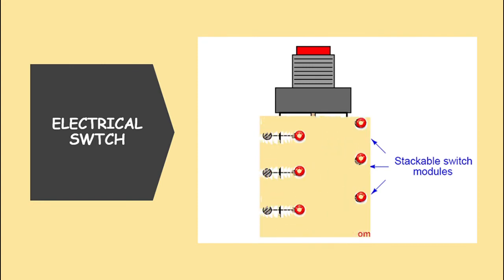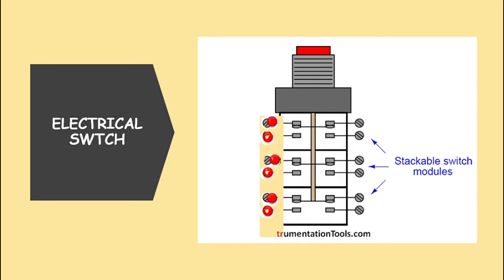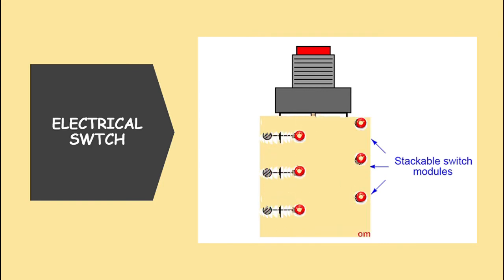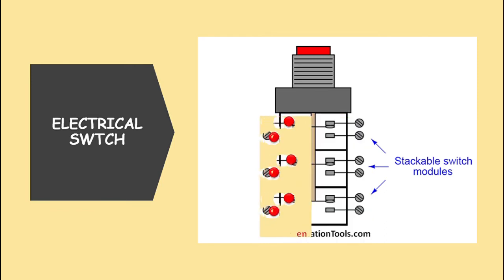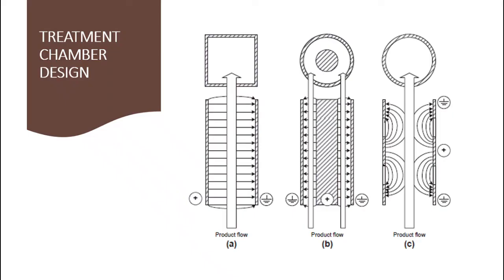These switches require less complex driving circuits and are easy to handle and control by external triggering, with optimum variability of pulse parameters. Limitations have been found in reliability in long-term use, in particular when exposed to reversal current in case of arcing, treatment chamber blocking, or electromagnetic interference. For high voltage pulses greater than 100 kV, a Marx generator is commonly used, invented by Marx.